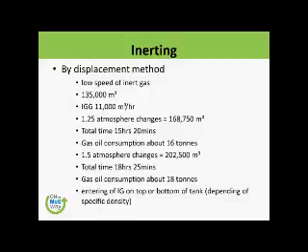But the biggest thing, we are running those generators on low sulfur diesel oil, which is an expensive commodity. Instead of running the generator for 15 hours 20 minutes, you are running it for 18 hours, and rather than burning 16 tons, you are burning 18 tons of expensive fuel. Your ship owner will not be very happy.